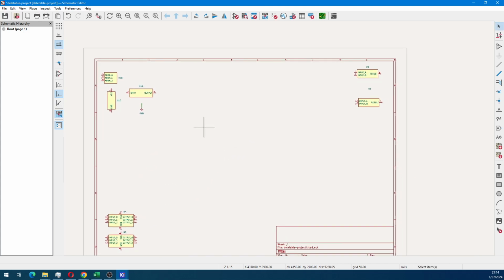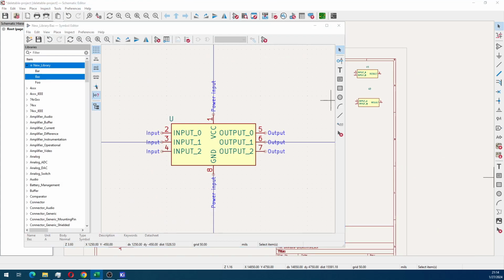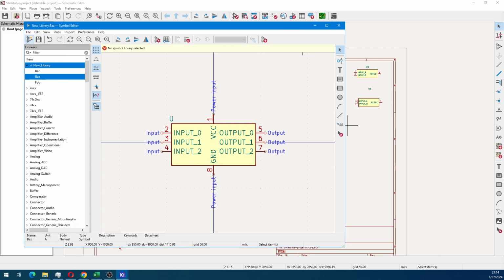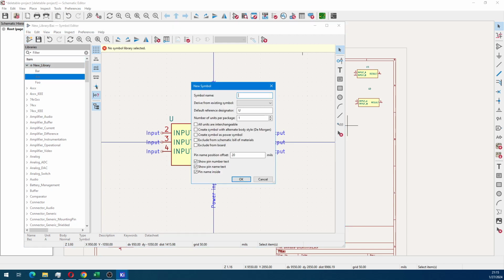Alright, so we are going to add a fourth custom part now by first selecting the library and then going to add new part. And what this new part is going to be is essentially a power port. So for example, a ground symbol is a power port, a supply voltage rail is a power port. There's also a third type that I won't get into until a later video. But power ports operate quite a bit differently from other custom symbols, or any symbol for that matter.